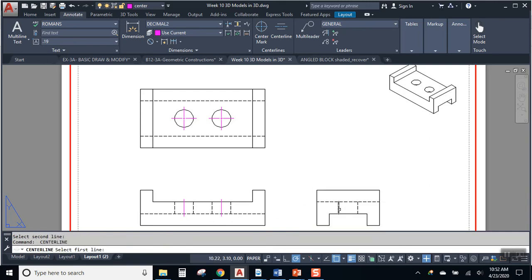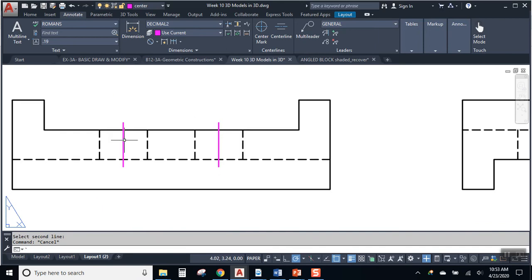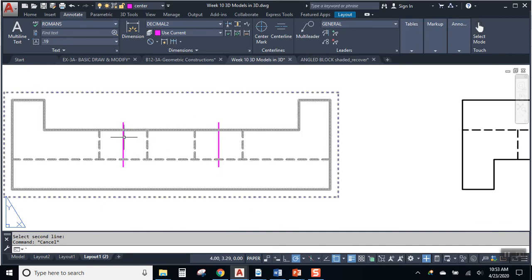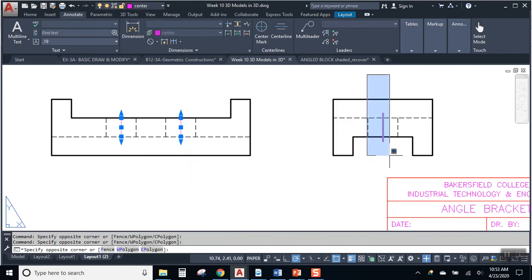And we'll have another one over here. And now, of course, if your object is small, just understand that center line's not looking much like a center line, is it? So you might need to go in there and make some adjustments. It's a property called line type scale, right?